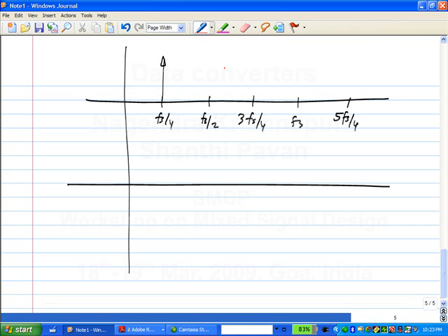If I have a sine wave at Fs by 4, the spectrum will look like this. It will have only an impulse. If I have some other periodic wave with a frequency Fs by 4, what components will it have? All integer multiples of Fs by 4. So in this case, we will have Fs by 4, which will look more or less the same. Then Fs by 2, 3 Fs by 4, Fs, 5 Fs by 4, and so on.